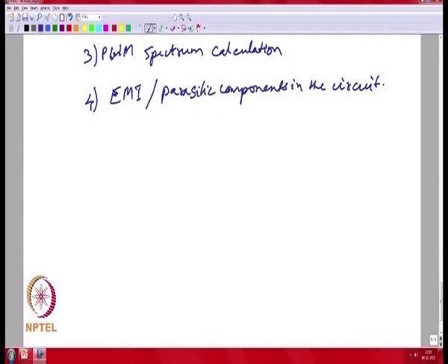You have lead inductances, and you have capacitance not just from the collector to emitter of your transistor switch, but also between your silicon chip and your heat sink. These capacitances can carry currents, and those currents can lead to significant EMI concerns in your power converter.